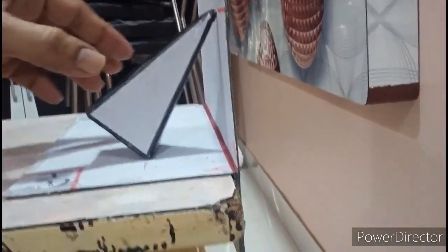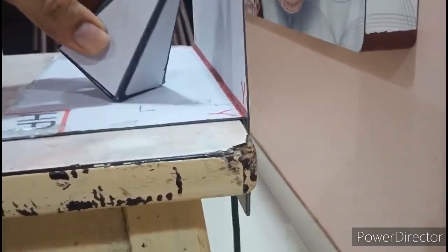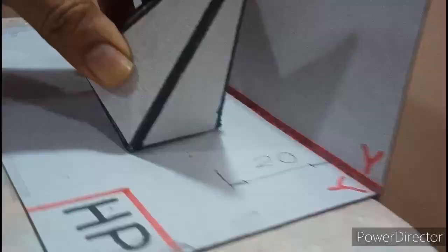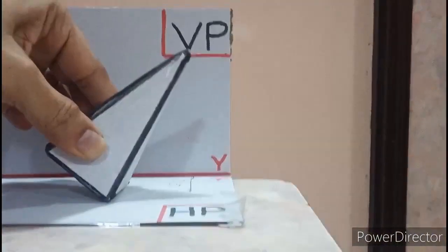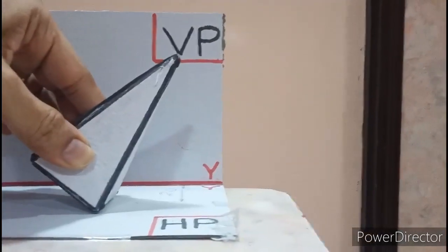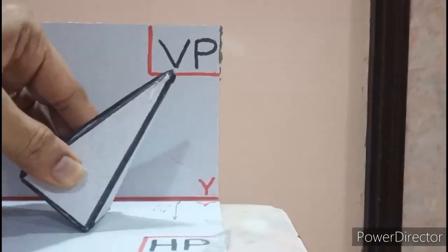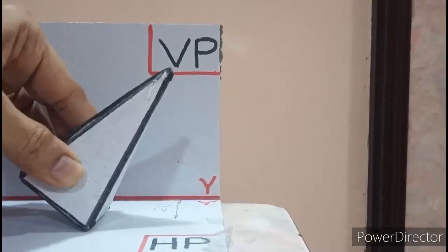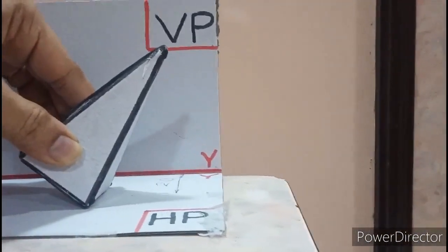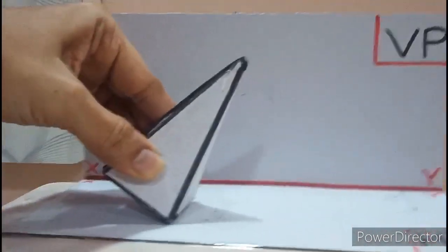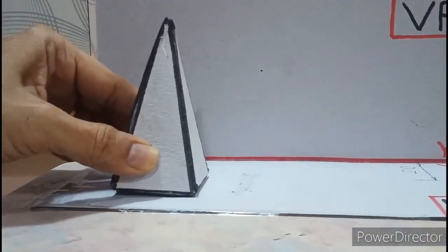Now focus on this 20. What we'll do is that to go back to the second stage without disturbing 20, I will not disturb 20 mm. I will turn this by 90 degree. So now if you look in the front view, try to understand what is 20 now. So if you project apex down, the distance of apex from base edge is still 20. And in the first stage, as usual, we need to make the entire base to rest on HP.